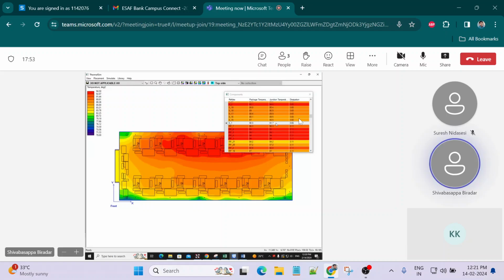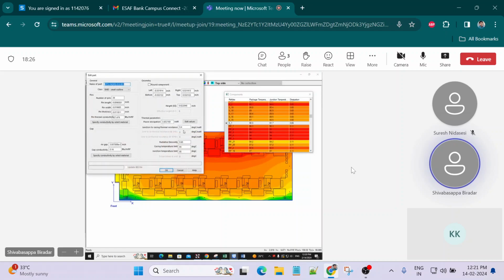Any further doubts? Suppose it fails, what do we do to make it pass? Generally, for leakage and such, we introduce decoupling or pull-down, pull-up resistors. But in this case, we will inform the customer to reduce the power dissipation value, because once you reduce the power dissipation, the junction temperature will also reduce.